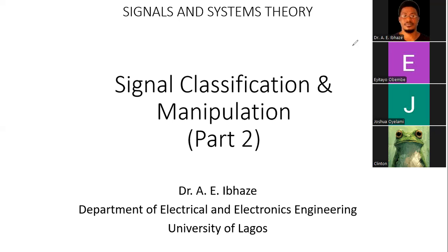And then we also mentioned that the conjugate antisymmetric signals could be used to realize odd signals. And I want to mention that they could also be used to achieve Hilbert transforms and phase manipulation.